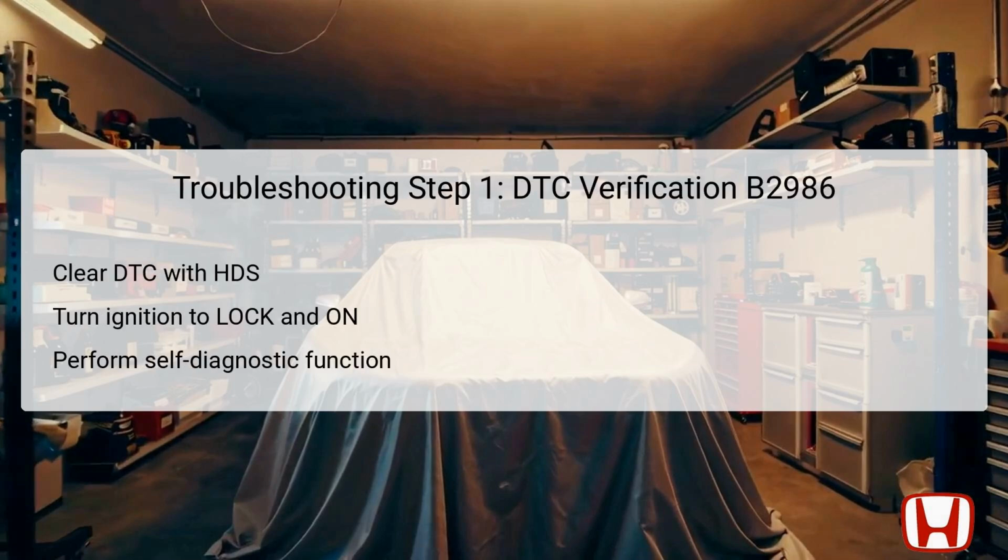The first step in troubleshooting DTC B2986 is to verify the presence of the fault code itself. You can start this by clearing the DTC using a Honda Diagnostic System HDS scanner. Once cleared, turn the ignition switch to the lock position and then back to the on position, or alternatively, use the engine start-stop button to select the off mode and then return to on.